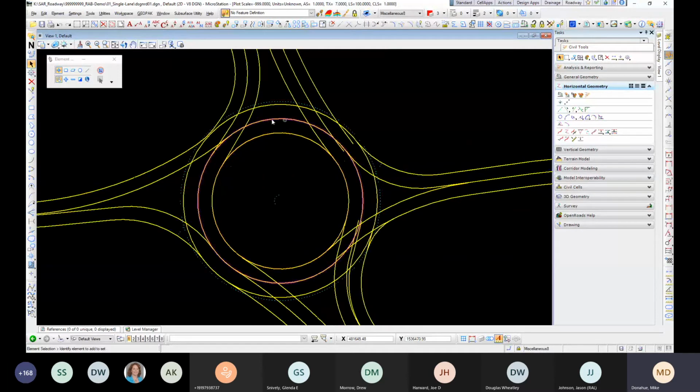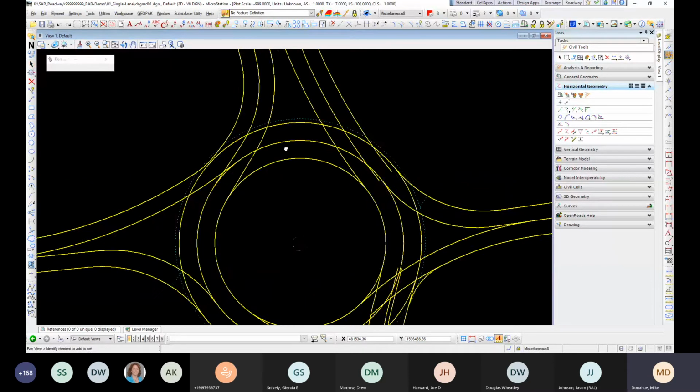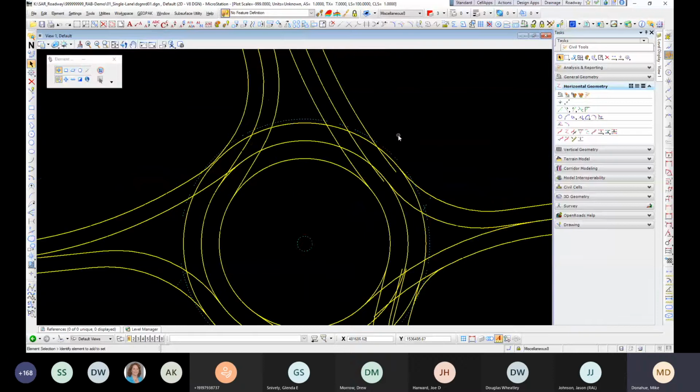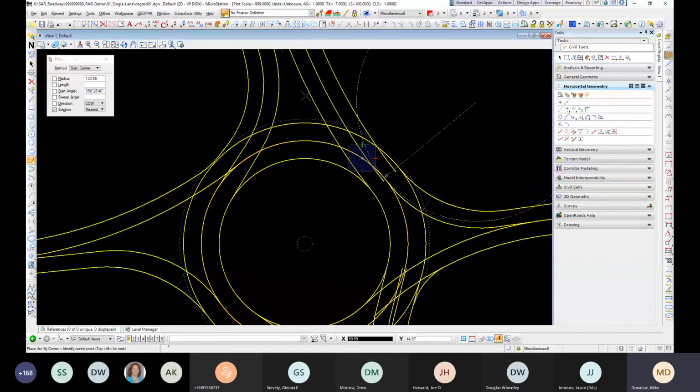Like I said, this area in here, you're really going to only have probably one lane exiting. So one of the ways you can do that, at least one of the ways I like to do it, is I'll set, I'm using already a different level. So back to using MicroStation lines instead. You can draw a tangent to this element. Start in mid. Tangent to this line, come off tangent to your exit line, and begin at roughly where this median nose is going to be.